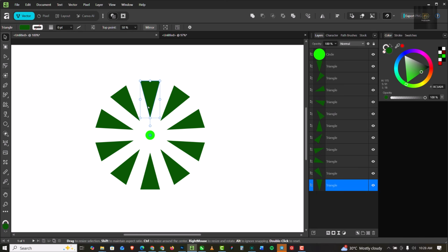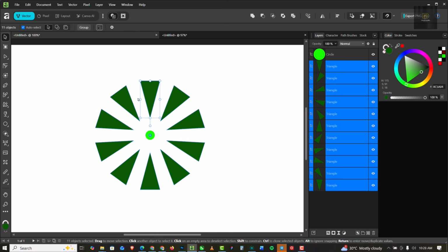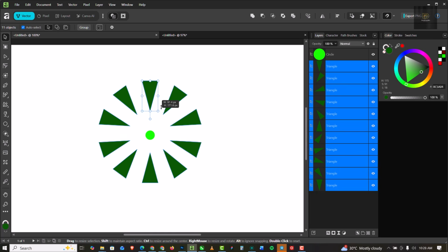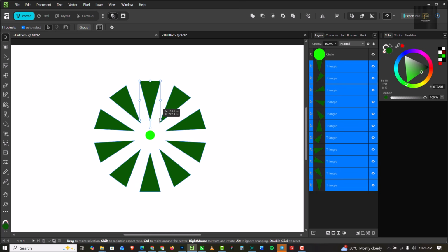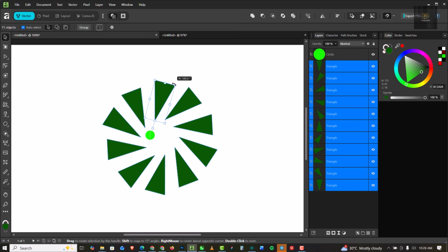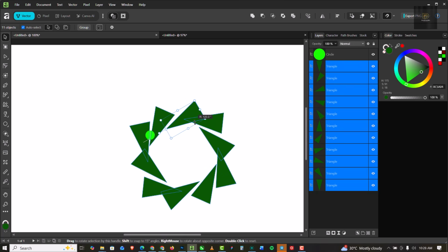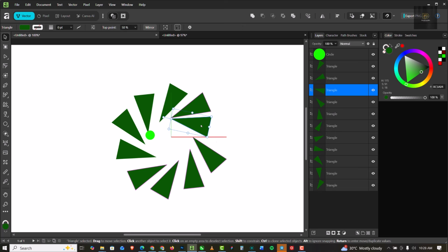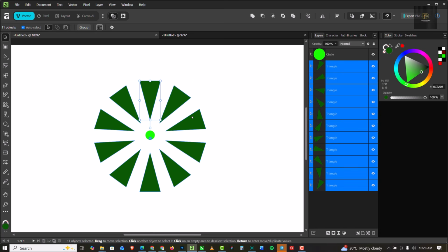Now, if you want to adjust all of these things, very, very easy peasy. Make sure you click here and here that says transform objects separately. So you can hold down your shift key. Before you do that, you can select all of them and you can pull this in or outward any way you want it. You can have it this way any way you want it, right? Or you can choose to rotate this. You can see that rotating it is giving something else different from what we have. So you can make this work for yourself basically.